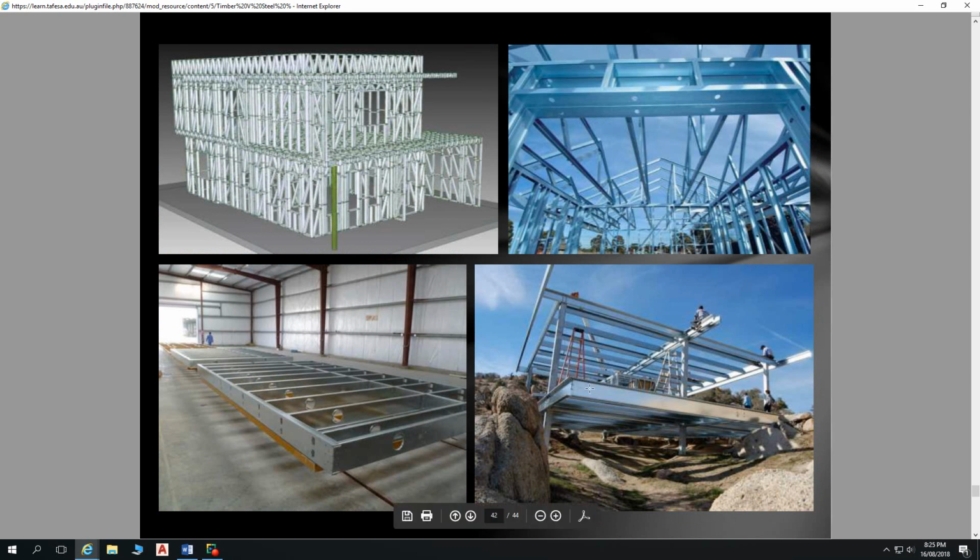This here is what's called hot rolled steel framing, and that's another, okay, very expensive. In the main, it's going to be cheaper to do something like this than something like this, because you pay a lot of money per linear meter for those beams. You get prices from your various different steel suppliers. Very expensive per linear meter. Also very difficult to manhandle on site. Takes either a lot of people, or typically you use a crane.